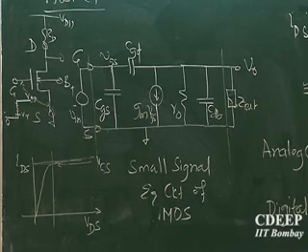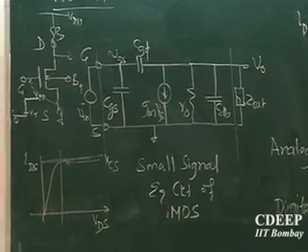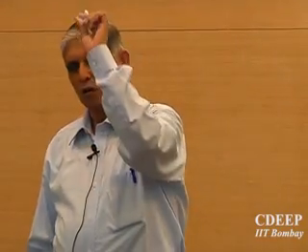Is that clear to you? So this is in digital, the state of the device varies as the input starts rising from low to high or changes otherwise from high to low. Is that correct? So in the case of digital, you have to figure out every time what is the status of a transistor and then correspondingly use the IDS equation, whether it should be the non-saturation current or the saturation current. Is that clear? Whereas in analog, the device will always remain in saturation. For BJT also.